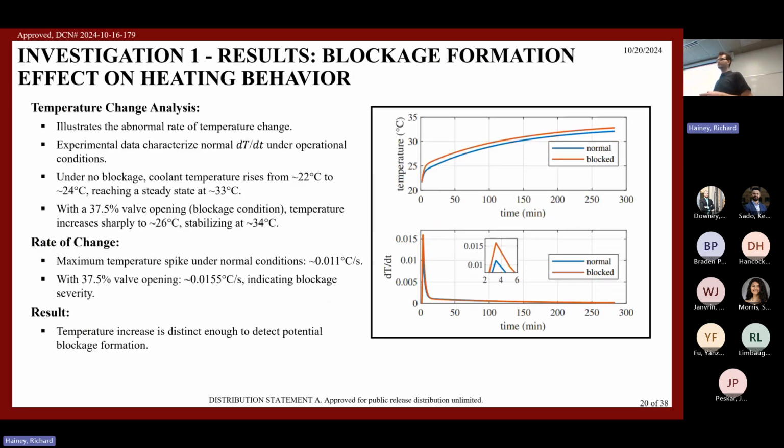So using the information from here, and if you are using a human in the loop system, because we didn't have any automatic way of detecting blockages or abnormal heat behavior yet, an operator could observe this information data flow and use that to determine if there's an abnormal loss of coolant within one of the converters or multiple of the converters. Of course, the problem with this is you always need an operator to observe them.